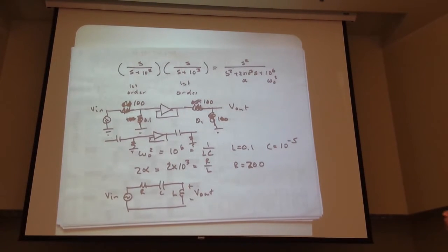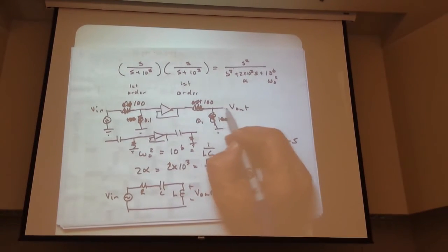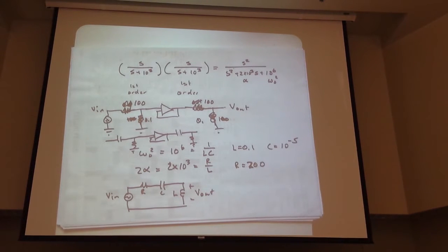In a large sense, though, which component are you more likely to see used? Yeah, capacitors. Inductors are more problematic, typically. So more often, you would build this with a capacitor. Yeah? Do we have to consider the fact that it blasts out at 10 dB? Oh yeah, I left off my gain. You're right. So I need an amplifier here. I need about 3 times gain.